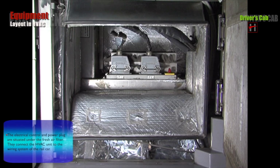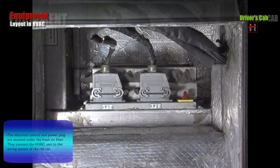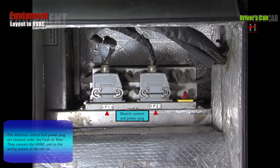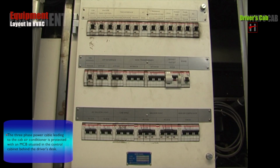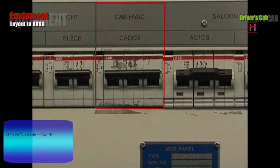The electrical control and power plugs are situated under the fresh air filter. They connect the HVAC unit to the wiring system of the rail car. The main control switch is mounted next to the plugs. The HVAC unit stops working with the switch in off position. The three-phase power cable leading to the cab air conditioner is protected with an MCB situated in the control cabinet behind the driver's desk. This MCB is labeled CACCB.